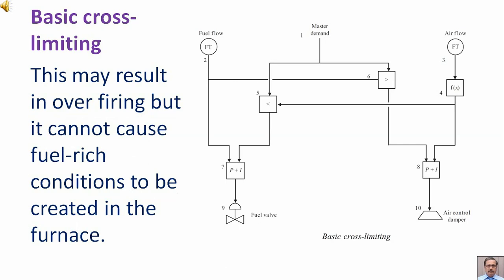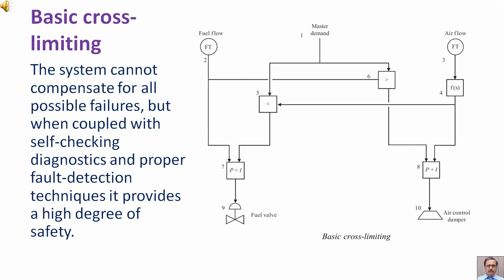This may result in overfiring, but it cannot cause fuel-rich conditions to be created in the furnace. The system cannot compensate for all possible failures, but when coupled with self-checking diagnostics and proper fault detection techniques, it provides a high degree of safety.